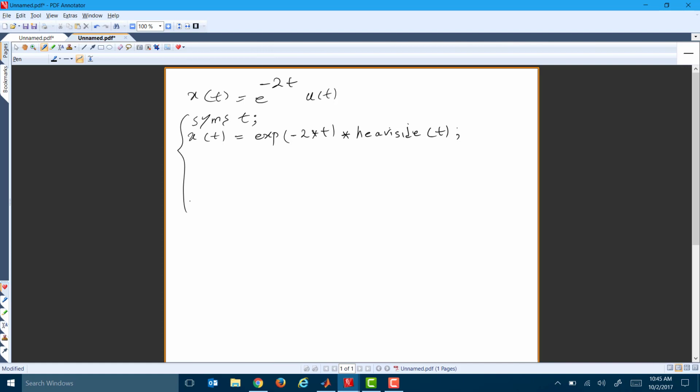So basically it's telling MATLAB, for now, ignore the fact that t is undefined. You are telling MATLAB that I'm going to give the t variable to you later when I want to plot it. So let's say now it's the time that I want to plot this function in MATLAB. Then I go and I define the variable t. Let's say I want to plot this function from the range of minus 10 to 10. So t is defined at this moment, after writing the function.